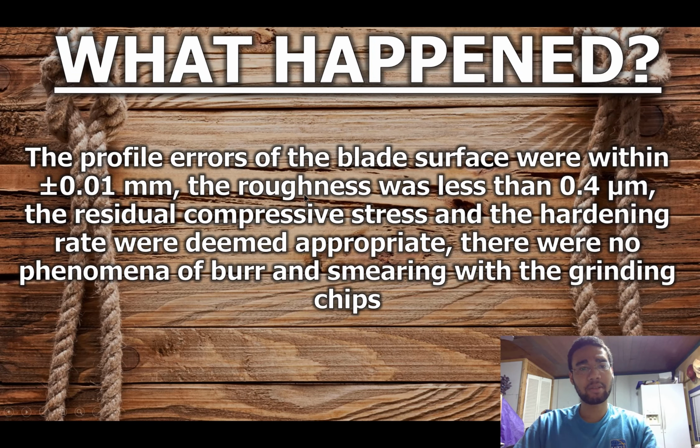So what happened during their project? The profile errors of the blade surface were within 0.01 millimeters. The roughness was less than 0.4 micrometers. The residual compressive stress and the hardening rate were deemed appropriate. There were no phenomena of burr and smearing with the grinding chips.